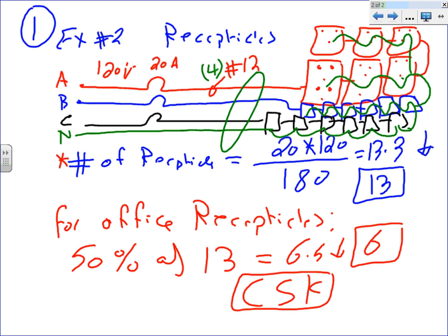Yes, it's shared, but it's highly unlikely that everybody using these circuits will be energizing them fully at the same time, guys. So you take advantage of the diversity of the load. They call it diversity of the load. Highly unlikely that the people will be utilizing all these receptacles, all of them, fully at the same time. But it's highly likely that Chad Kearney will be plugging multiple things in, sitting in his office and goofing around here, right? One person. I can't emphasize this enough. Is this directly related to how we're going to be circuiting? Any question, my friend?